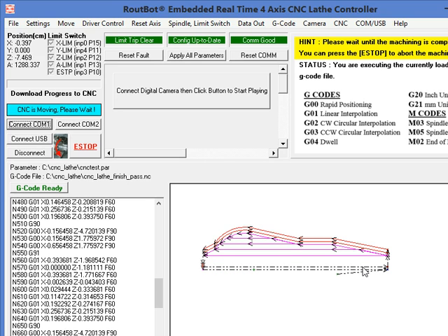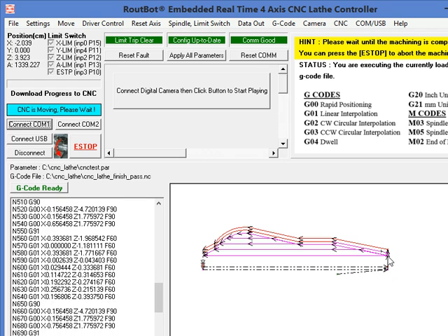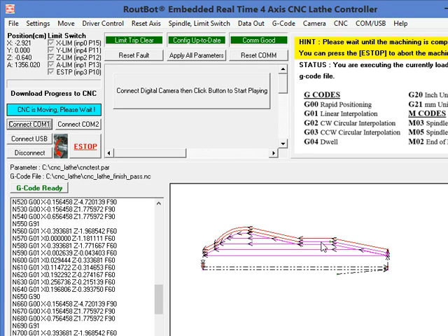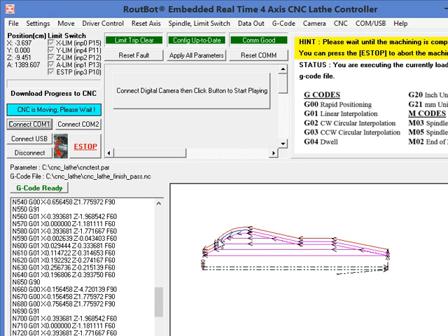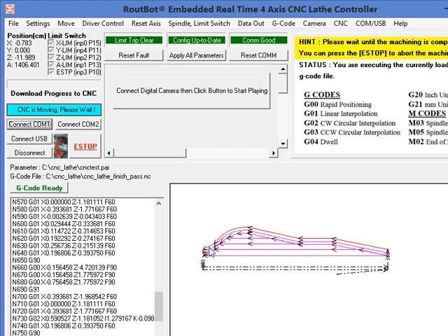Now, what is interesting, the CNC will now follow the path for the finish passes. The finish passes are different from the roughing passes because the finish passes always execute the profile as is. So it's really going to execute the profile as is and go inside by the amount that was specified, which in this case is 0.1 inch. So now there's only 0.1 inch left before we get the final result of what we want.